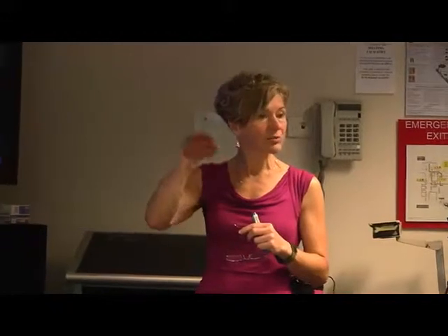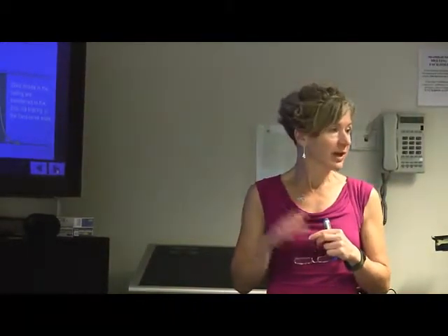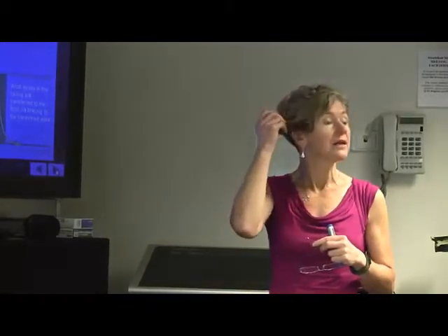The walls therefore have to resist deformation due to the wind loads, and they tend to resist wind loads by having bracing panels or cross bracing in them. And I'm sure you've seen those two different types of bracing in walls, and the little model outside has some bracing panels on it, but whenever you see a building going up, you'll see panels being used and often the cross metal bracing.